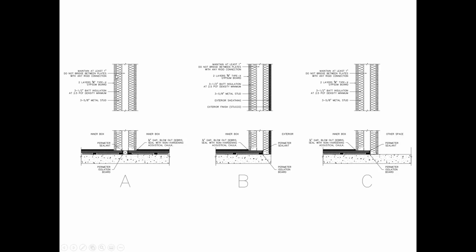Like, okay, we know this wall produces STC 70. I think it's probably close to 65. That one's more like 65 to 70, somewhere in there. Depends on how big your air gap is. But it's pretty easy just to get a wall that has a good STC rating and you think this will work. The devil is in the details though.